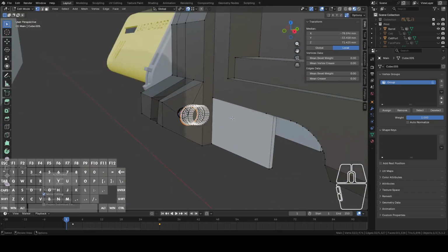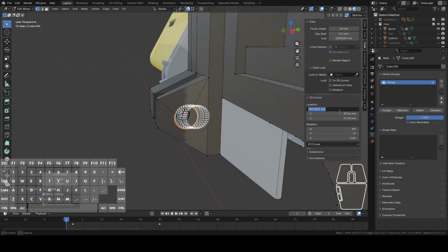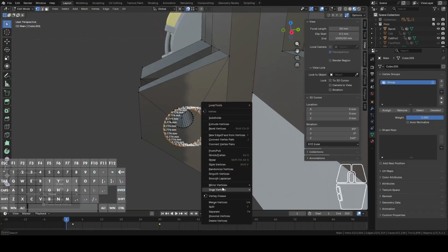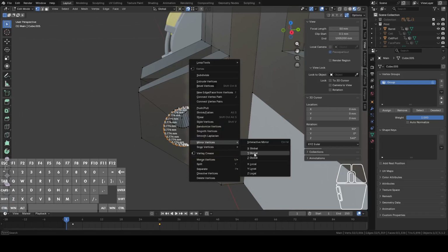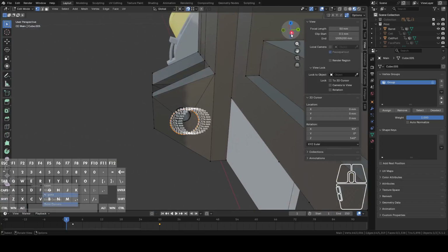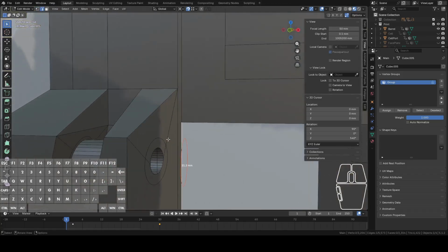And since it's no longer mirrored, we're going to have to put this on both sides. So let's go into View and center our 3D cursor. That way, when we use it as our pivot point, we can duplicate this and then mirror the vertices along the Y. Mirror Y. That way we should have it on either side. And then from here, get into this orientation, hit P, separate selection, and then we'll knife project. Little details, but I like the little details.